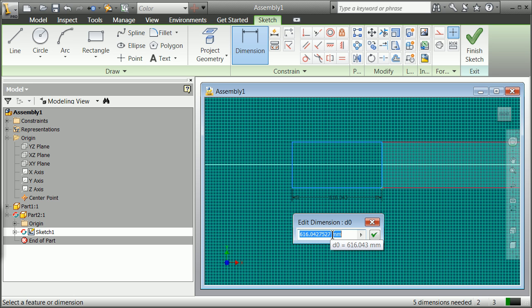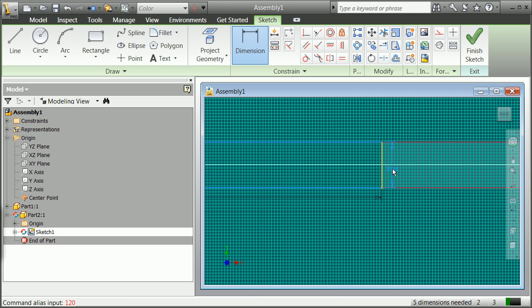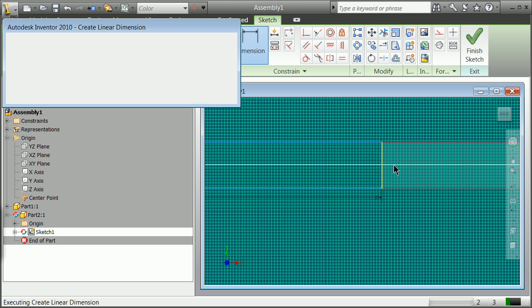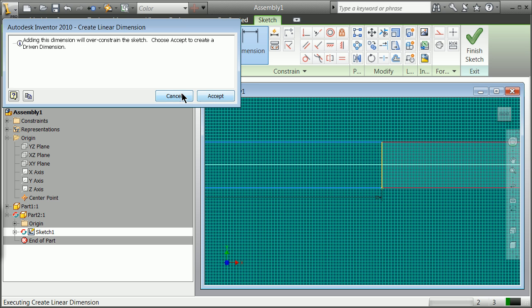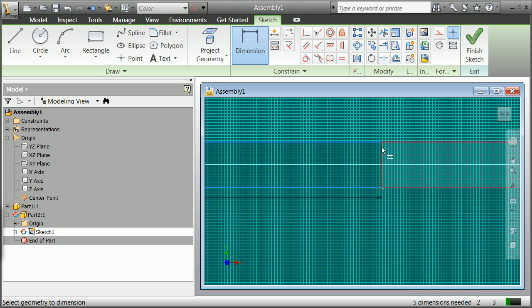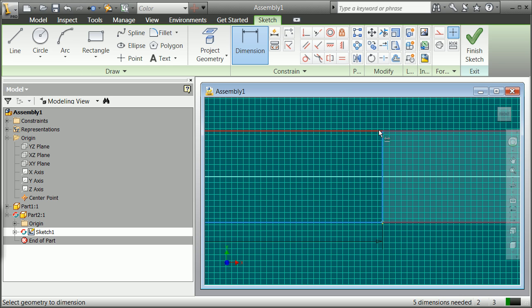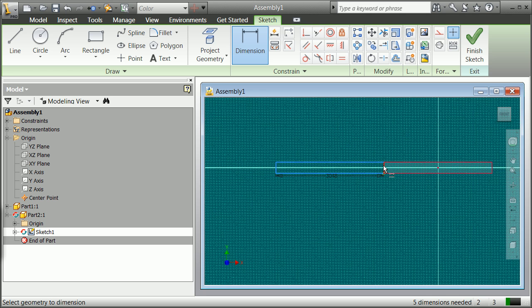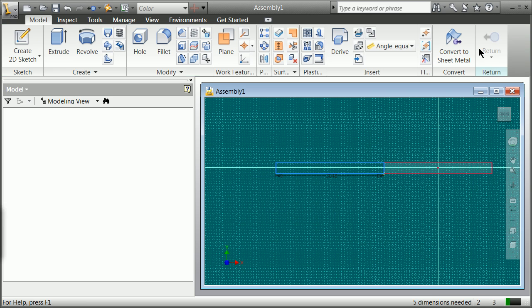I'm going to say it's millimeters, and boy, I don't know coming in whether you can just type inches here, but we'll try it. 120 inches, which is taking that out that way. And then the dimension here is, again, 120 inches. So I'm going to click on that, double click on. It's actually over constrained, so I think it grabbed it already. So you're going to see that the way I laid it in, that was going to be done here. I can now say finish the sketch.